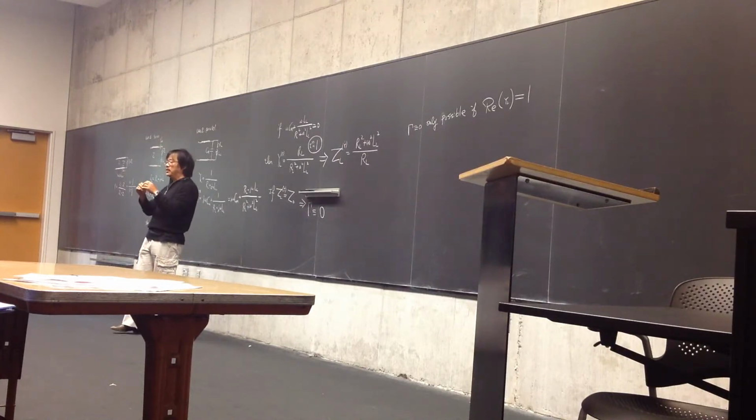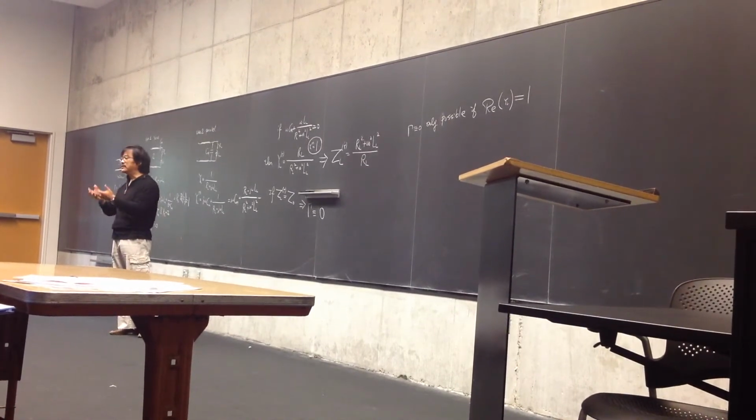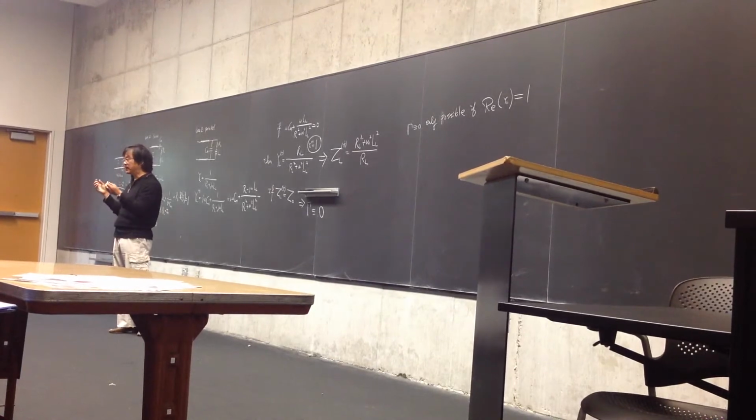But I'm talking about the total admittance. The true admittance will have an imaginary part. That's where you add the circuit component to cancel. It doesn't matter how big or how small the imaginary part is, you can always provide a capacitor or inductor to cancel it out.